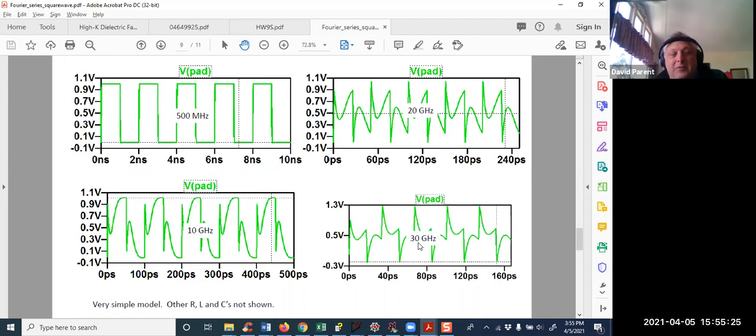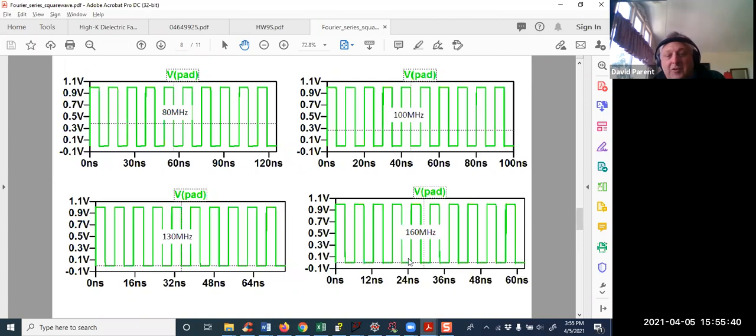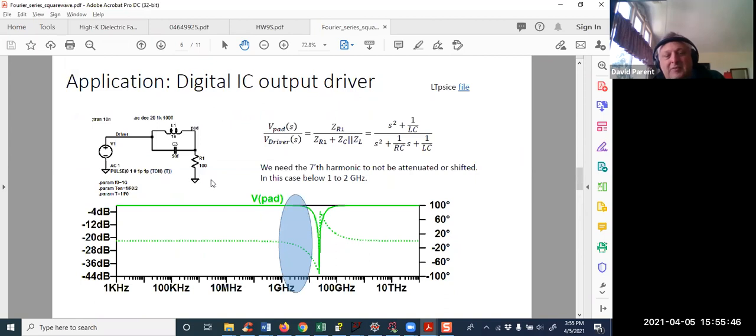Okay. So in general, that's why to get a signal off and on a chip, you're kind of limited to 130 megahertz. This example kind of shows that, you can go faster, right? But that's because the example parameters are such that it's not happening at that. Also, the faster you go, there's like a power consumption, and the chip would heat up, and you couldn't use it. So really, kind of almost the fundamental limit of how much you can do on a chip is actually how much heat it can dissipate. All right.